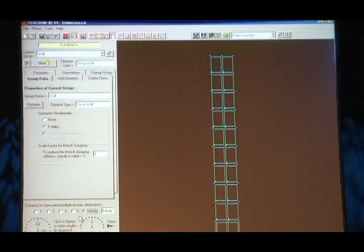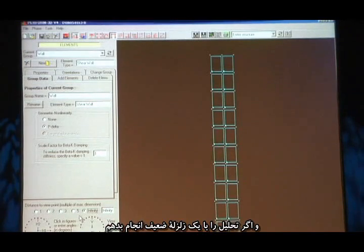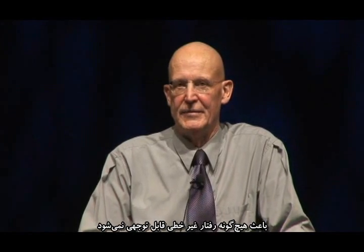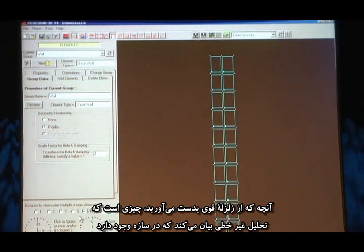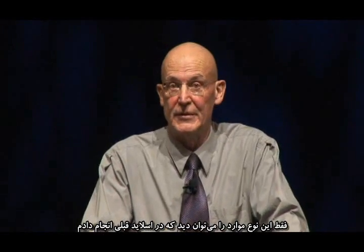And the point is this: I've run an analysis with a strong earthquake, which causes the hinging at the base, and then I've run an analysis with a weak earthquake, which doesn't cause any significant nonlinear behavior. So the moment envelopes you get from the weak earthquake would be the sort of thing that you would design for if you were using linear analysis. What you get from the strong earthquake is what nonlinear analysis says would be present in the structure. Now, I can't compare the numerical values because one is a weak earthquake and one is a strong earthquake, but I can compare the shapes, just the same kind of thing that I did in the previous slide.